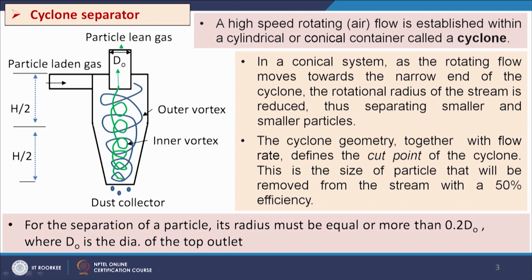Actually, the particles will move from the center to the outer side, and when a particle reaches the outer side, it is arrested here, its radial velocity will be 0 and the particle will fall. So, this is the mechanism for the separation.